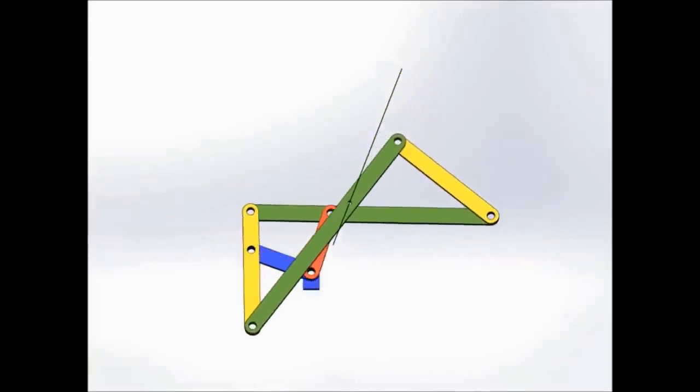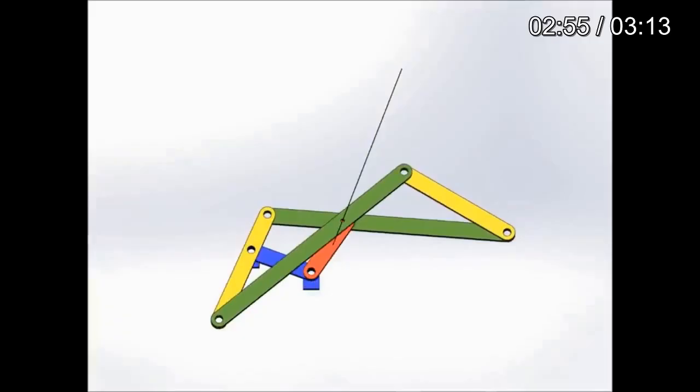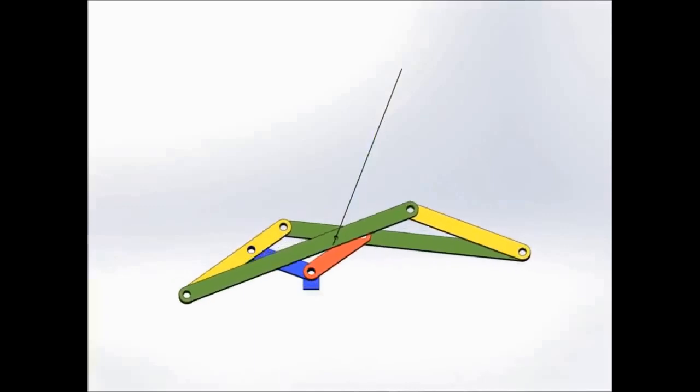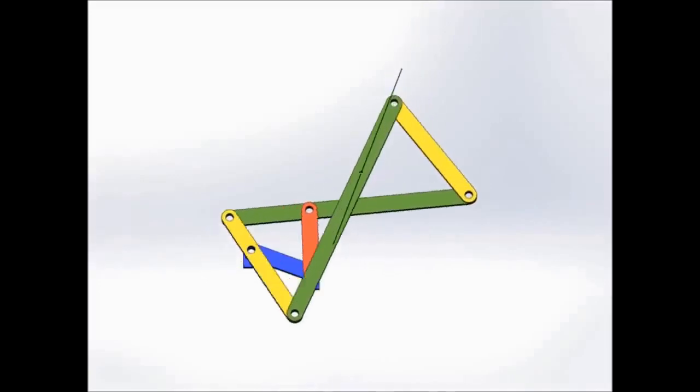Now this is another straight line mechanism. This is called the Hart mechanism. Please note. Here the conditions are actually again that these two green links are equal, then again two links are equal, and so on. For the Hart mechanism, whoever is getting the Hart mechanism can contact me, and I will give you more detail of this. This is tougher than the Peaucellier mechanism, and I will explain it to you. This is the Hart mechanism, the second perfect straight line mechanism, or exact straight line mechanism.